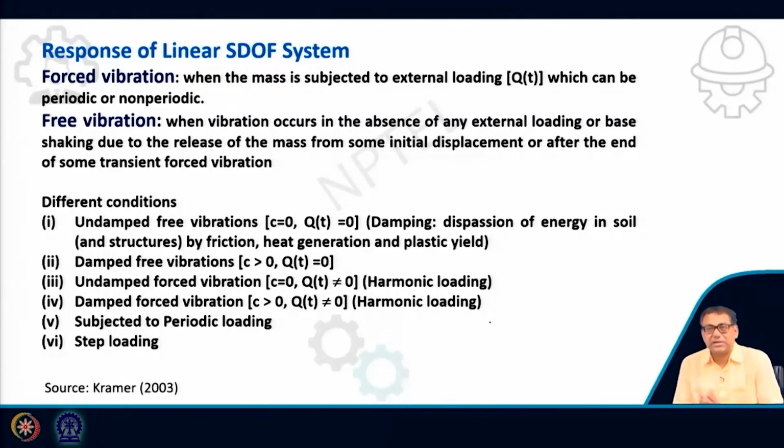Now, what are the different conditions? There is the damper. First, free vibration in the undamped condition, when the damping is 0, because we have seen the basic equation: mass into acceleration plus damping into velocity plus stiffness into displacement, equal to external loading. If external loading is 0, that is free vibration, and if undamped, the C value is also 0.